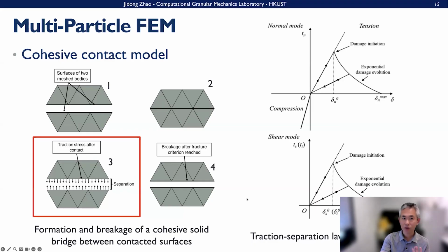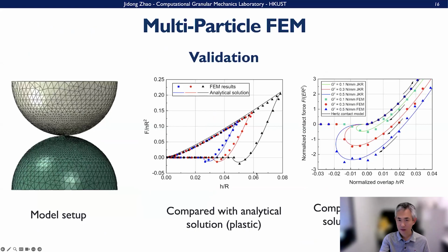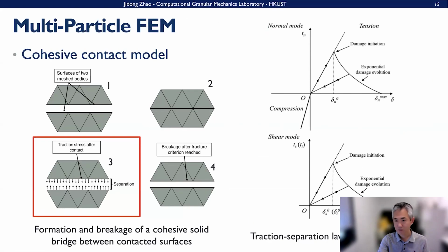So we also consider the cohesive contact here, in addition to the normal contact like in the Hertz model or Hertz-Mindlin model or these other models here.